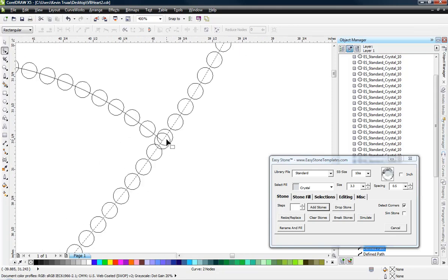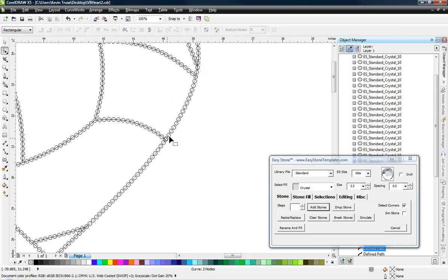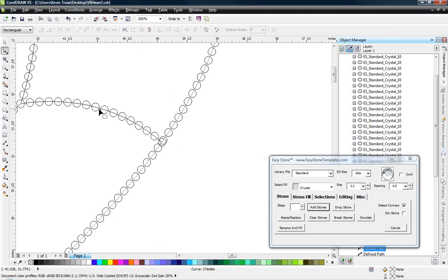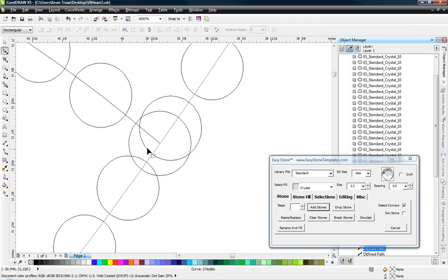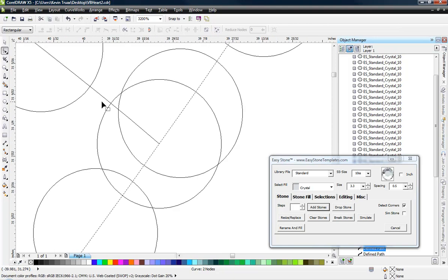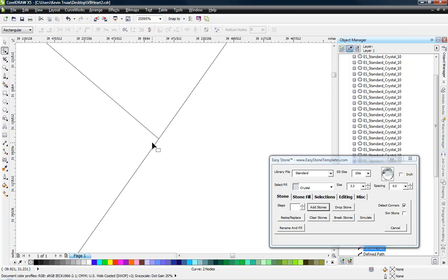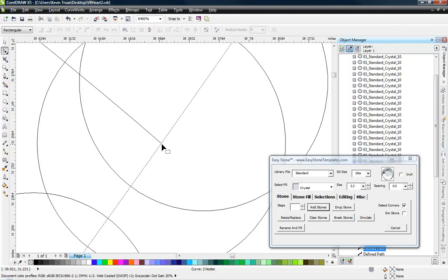And I'm going to back out a little bit here, and what you're seeing here is where this line intersects our outline. This is one continuous piece. It didn't catch that intersection. And it may be when I drew the line, I didn't actually draw it to the edge. Remember I kept telling you, you make sure you're on the edge. And while visually it looks like it's on the edge, maybe it really wasn't.